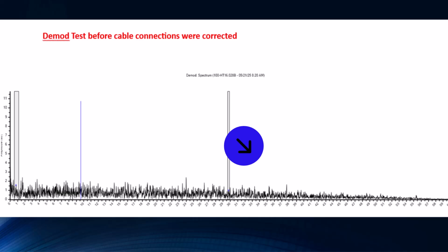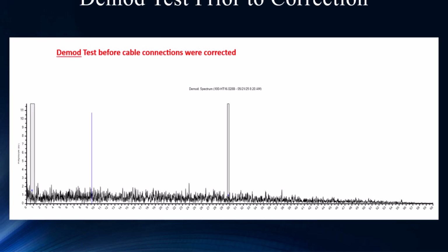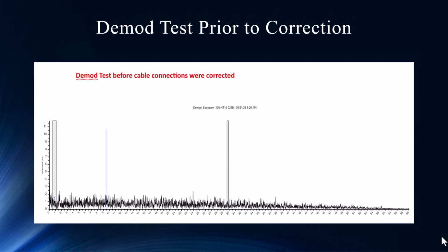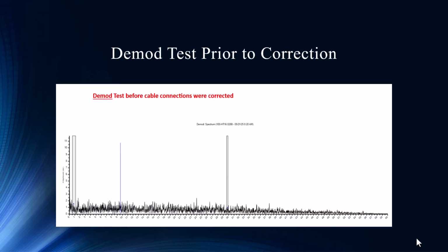It's almost like on our power test, we have the fundamental voltage and the fundamental current, which is essentially the 60 hertz signal. But then we also have the total, and that's a combination of all the harmonics. Right, that addition all the way to the top could exceed the FLA or the voltage. Absolutely.